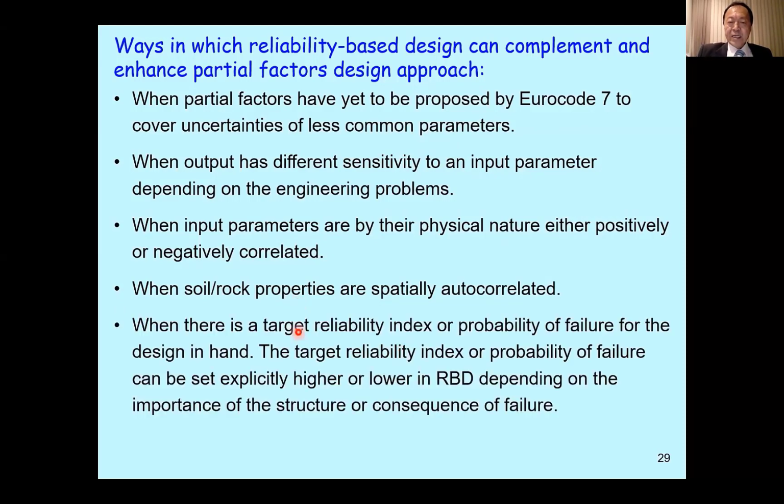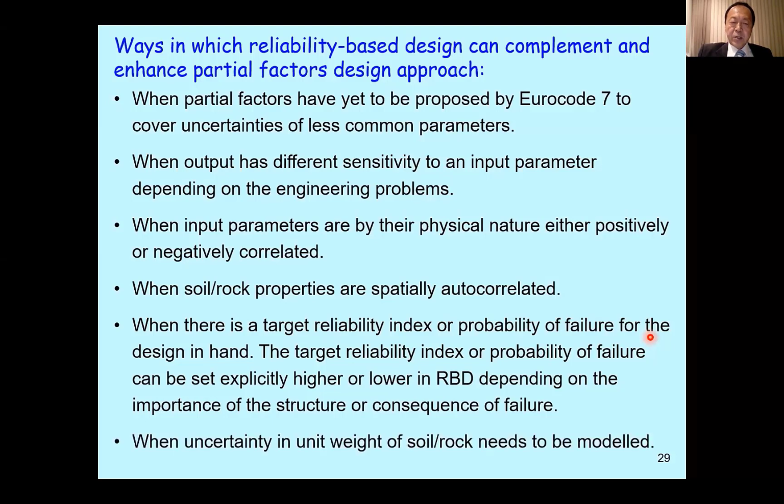And also then you can have explicit target reliability index and probability of failure, instead of LRFD, which does not convey information on probability of failure. So in this way, reliability-based design can complement LRFD and Eurocode 7. I say complement, not replace, because Eurocode 7 and LRFD are easier to use for practitioners and easier for them to understand.